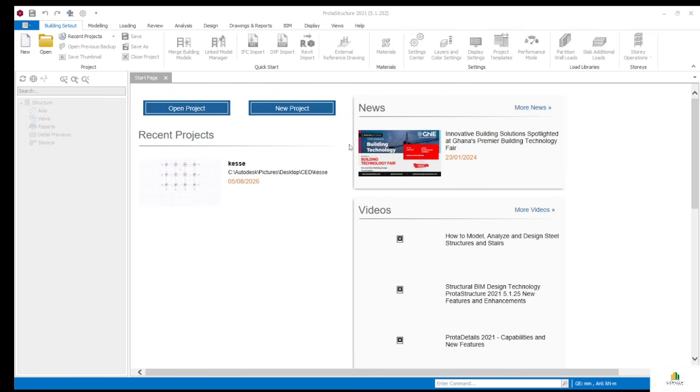Then you see template, you see search. So you see all the codes that you'll be doing. You scroll down to look for UK BS8110 or UK Eurocode, as I taught you how to use the code. In case you are using the Eurocode, you use the Eurocode throughout. In case you are using the BS, you use the BS code. So now let's use the BS.